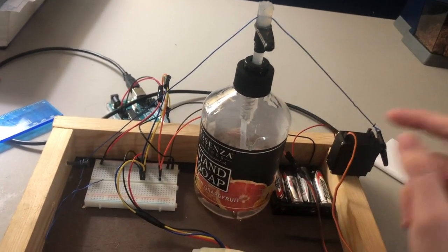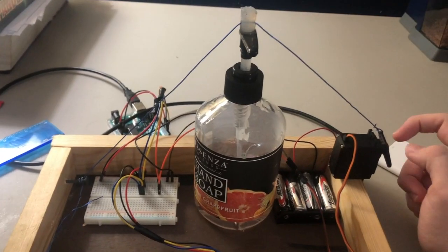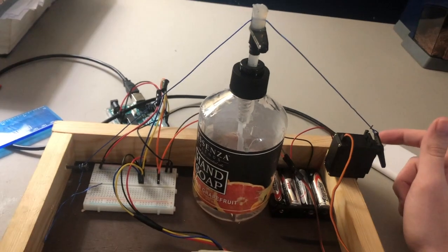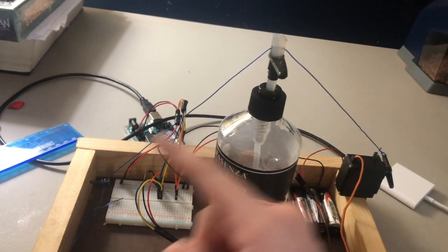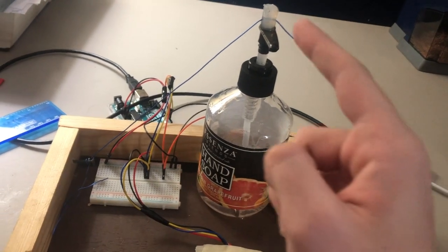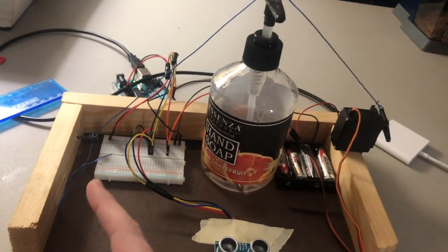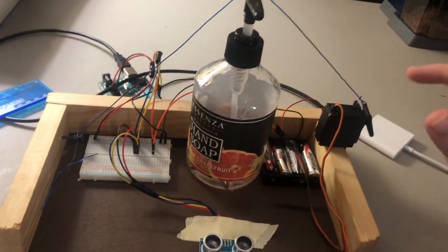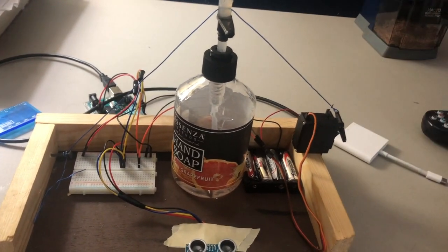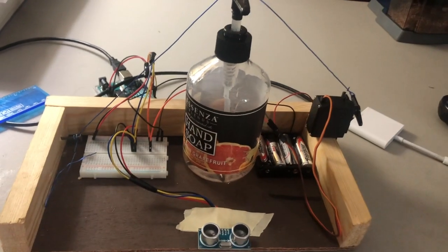hand soap nozzle. So this will turn to the specified angle, and as it turns, it will put tension on this galvanized steel cable that's threaded through the servo motor, through the top of the nozzle, and then anchored at the other side. And when this is in tension, this rotational motion will cause lateral downward motion of the nozzle